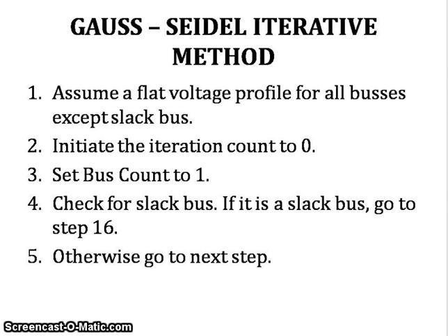So, as we need to solve a number of nonlinear algebraic equations, one of the methods proposed is the Gauss-Seidel method. It is an iterative algorithm to find out the set of possible solutions. Here the vector should converge within the permissible limit with prescribed accuracy. If we are able to achieve that, it means the system comes to steady state under given conditions. So there is one slack bus and n-1 buses are PV buses where the voltages and angles are assumed.